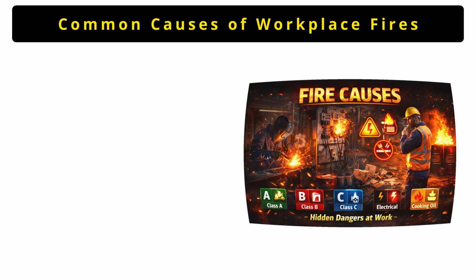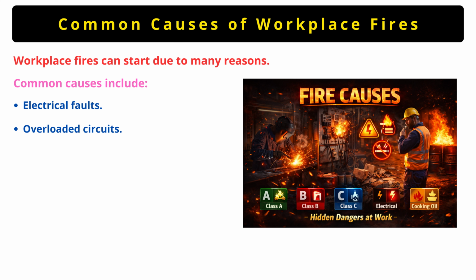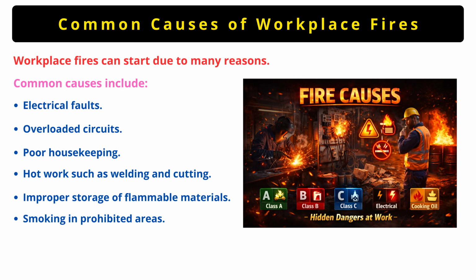Now, let's understand how fires start in the workplace. What are the common causes of workplace fires? Some common causes include electrical faults, overloaded circuits, poor housekeeping, hot work such as welding and cutting, improper storage of flammable materials, and smoking in prohibited areas.